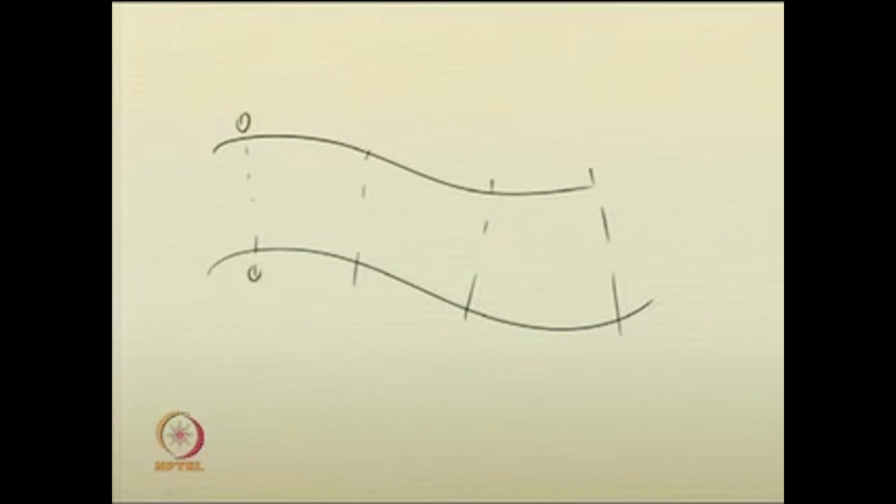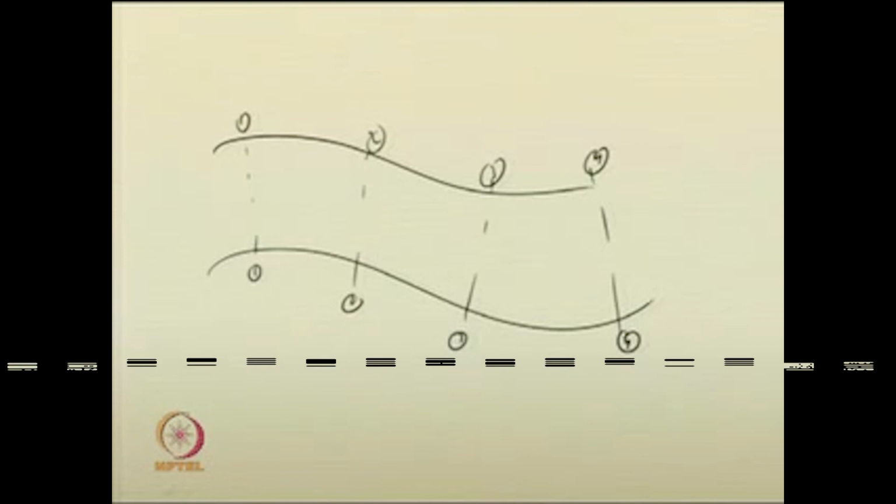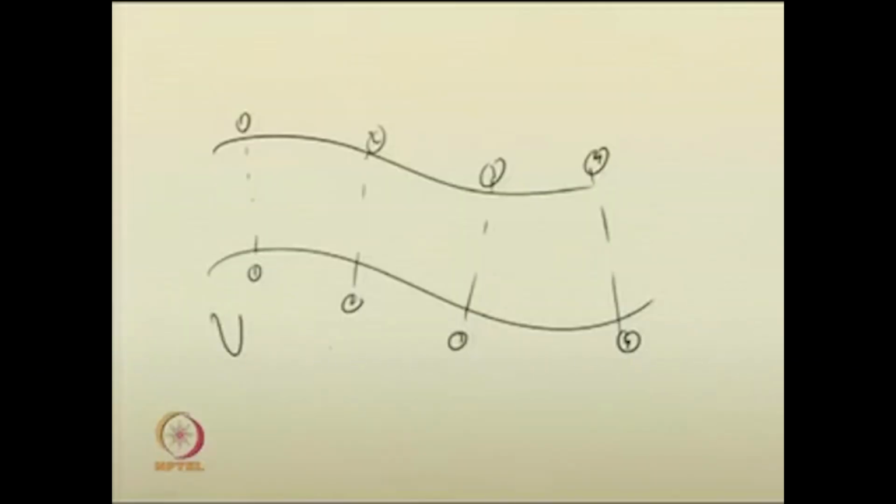Say this is section 1, this is section 2, this is section 3. Please note that this is the top view of a channel reach, a non-prismatic or natural channel, that is being given here. So, you do cross-sectional surveys, local field surveys. You measure the depth here, you measure the depth here, and the cross-sectional properties there, all those things will be recorded.